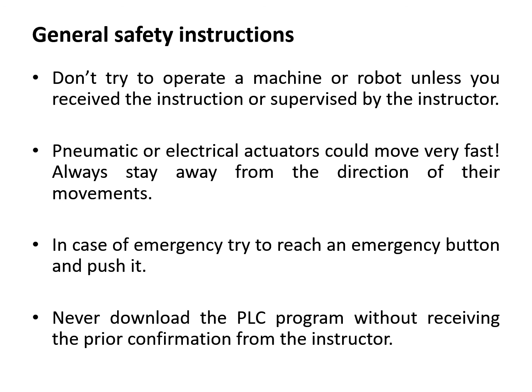Don't try to operate the machine or robot unless you receive the instructions or are supervised by the instructor. Pneumatic or electrical actuators could move very fast. Always stay away from the direction of their movement. Specifically, don't assume yourself an operator if you join a company just because you have passed this course or you have some knowledge about mechatronics.